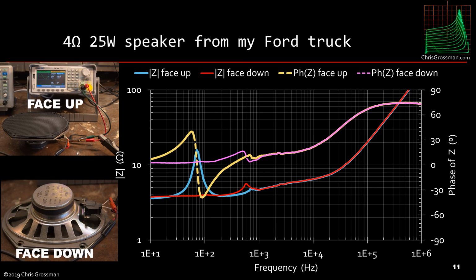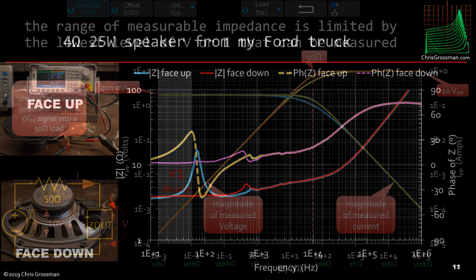As is true with most audio transducers, their impedance and response is very dependent on the audio environment they're coupled to. So if you put this speaker in a door where it was designed to be, you'd get a different response. If you had that door open or closed in the car, the response would be different. That's very typical, and now with this, it's very easy to measure and look at that response.